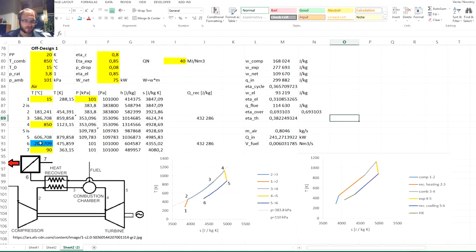First of all, we don't want this model to have this iterative loop, so let's just go back to having this temperature as the temperature at point 2 plus the pinch point, because by this we don't have really that high an error.